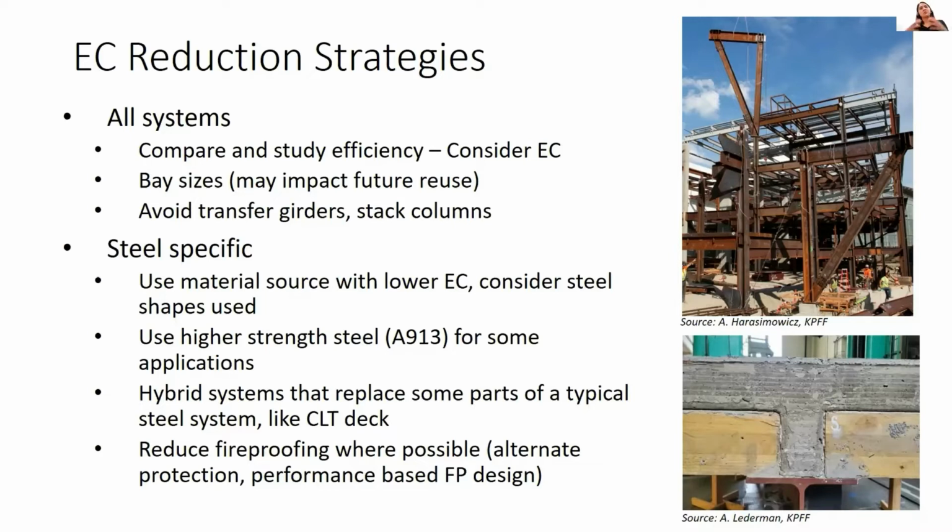Oftentimes we need to coat our steel with fireproofing, which is essentially a cementitious material. And as we know from looking at concrete, cementitious material has a big impact. So really study if there are ways to reduce the amount of fireproofing that's needed, although I would say there's no silver bullet fix for fireproofing.